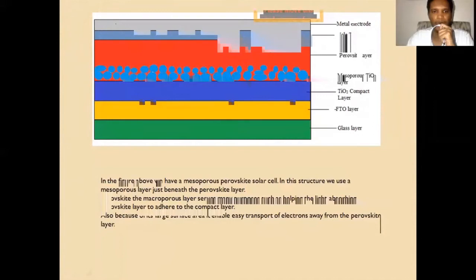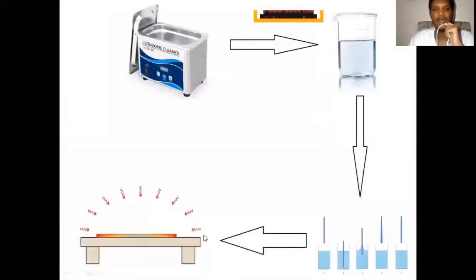After this, the precursor solution will be mixed using a magnetic stirrer for 20 minutes. Then the glass substrate will be coated using dip coating. We shall vary the withdrawal speed to see how our coating shall come out, whether it should be uniform, whether it should be transparent, whether it should be defect-free. Then we shall anneal our thin film at either 400 degrees Celsius or at 600 degrees Celsius.